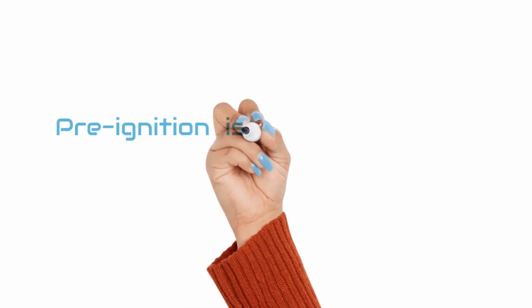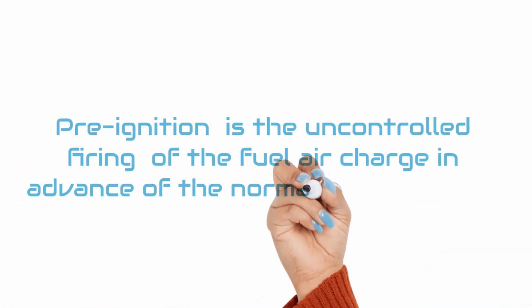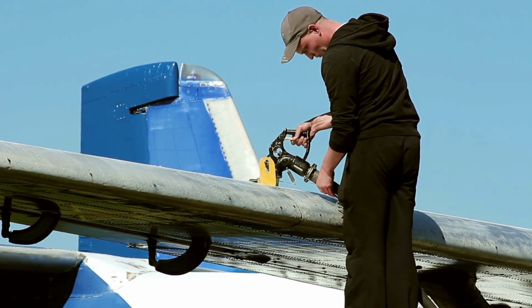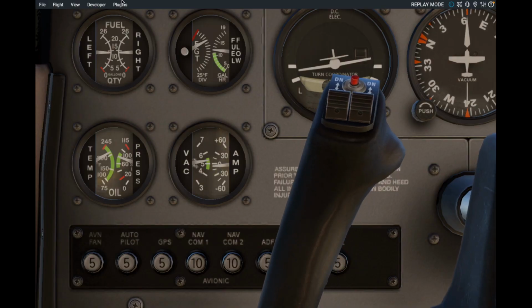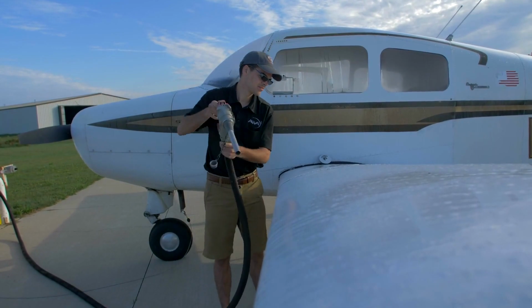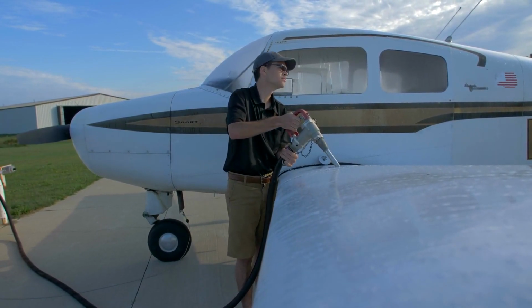A condition called pre-ignition is the uncontrolled firing of the fuel-air charge in advance of the normal spark ignition. Use of the next higher than specified grade of fuel is better than using the next lower than specified grade of fuel. This will prevent the possibility of detonation or running the engine too hot. Another thing you can do is fill the fuel tanks at the end of the day, because this prevents moisture condensation by eliminating the airspace in the tanks.